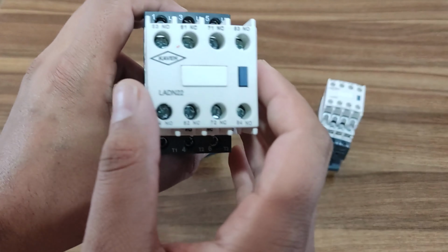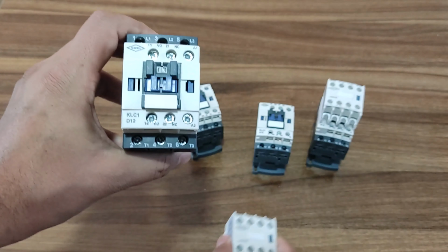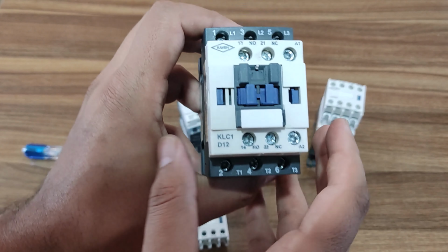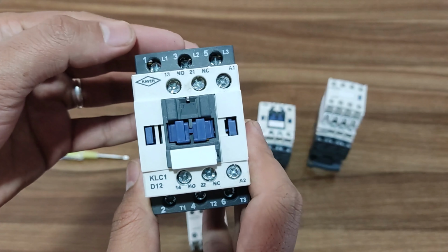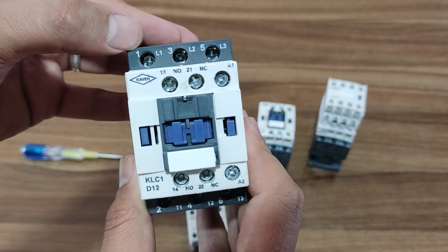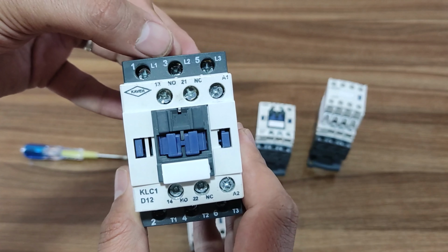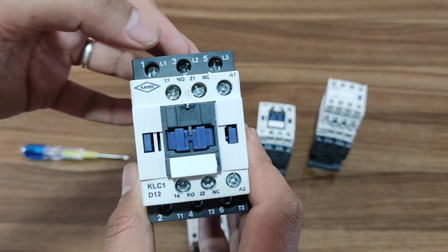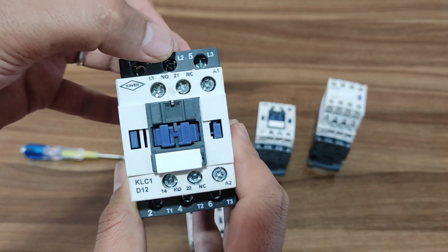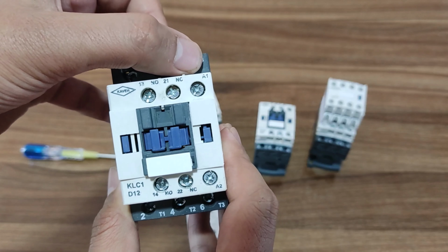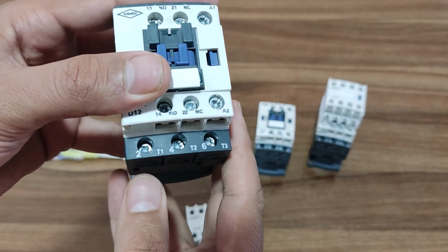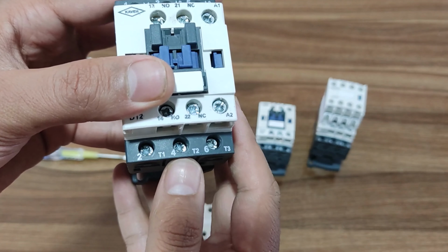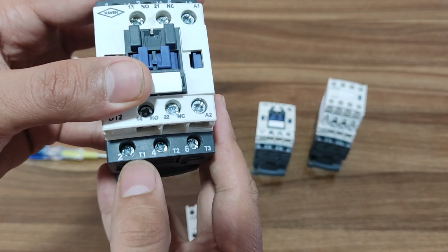Contactors usually have 3 input terminals and 3 output terminals to connect the power circuit. According to the IEC standard, these terminals are marked on the contactor with numbers 1 to 6. Terminals 1, 3 and 5 are inputs and terminals 2, 4 and 6 are outputs of the power circuit. In other standards such as NEMA, input terminals may be marked with 1L, 2L and 3L and output terminals 1T, 2T and 3T.